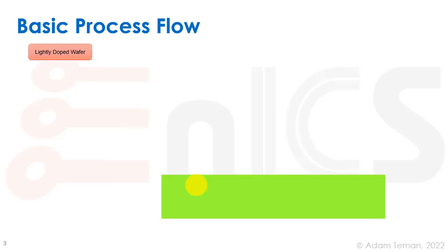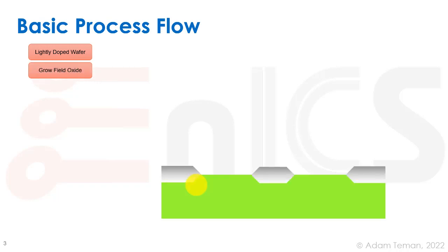So we start with a wafer, and the wafer is very big. It is not proportional to what I draw here, but this is going to be a very clean piece, usually of silicon. Usually, we really have intrinsic silicon that has no defects and no impurities in it, and then we do add some p-type impurity so we can have a p-type substrate. The first thing we're going to do is define our active areas by using a mask that helps us grow our isolation areas. These are thick oxide regions that isolate between the active areas, which will be over here and over here.